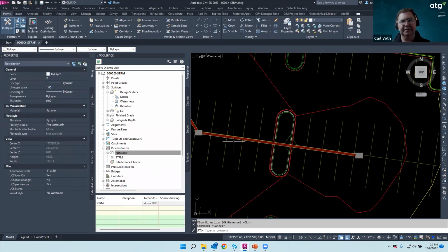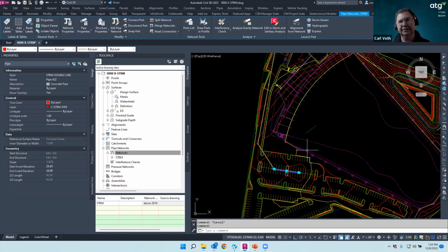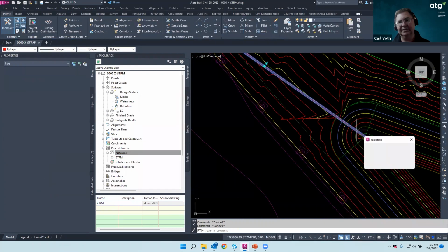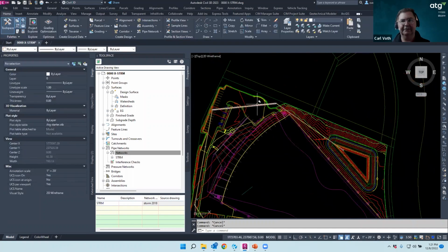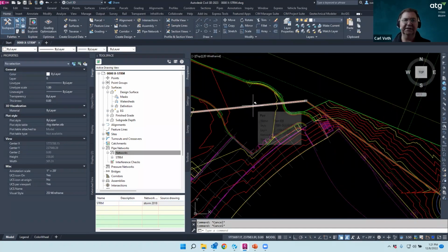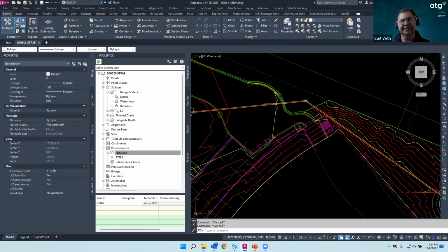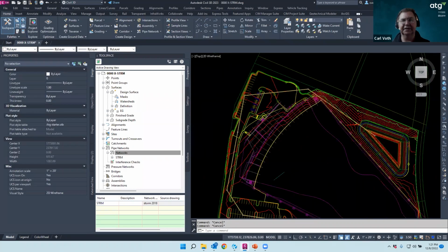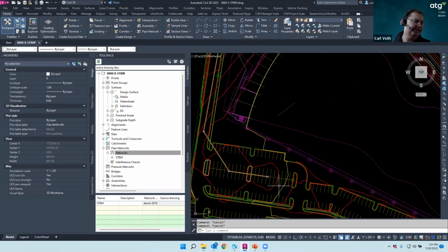And so now when it creates my pipes, you can see here, it's already got the elevation set the same as that feature line and the slopes. So unless there are design changes, I wouldn't have to go back and deal with the pipe properties or manually put in information there. And I just think the feature line quick slope editor is pretty easy to put that in.